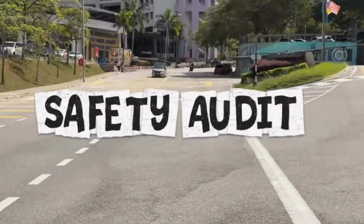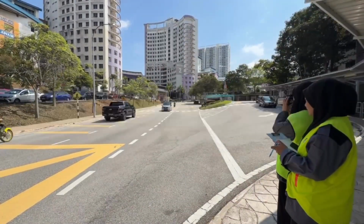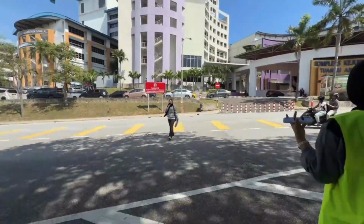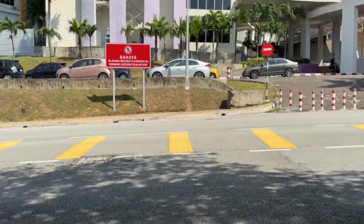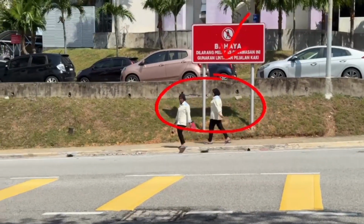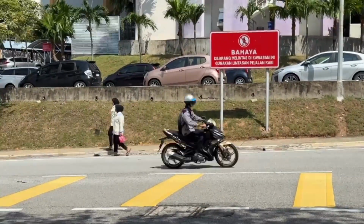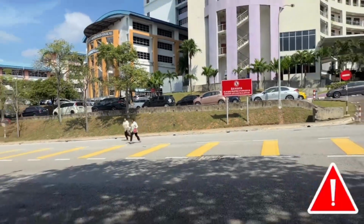We are Group 1 from Class ECG563 6A2A presenting our road safety audit for a critical vertical curve along Persiaran Institute UiTM Shah Alam. This location was selected due to several safety concerns, including limited stopping sight distance caused by the hill crest, increased vehicle speed when descending the slope, and potential conflict between vehicles and pedestrians. Although the pedestrian walkway is available, there are no designated road crossing markings to ensure safe crossing.